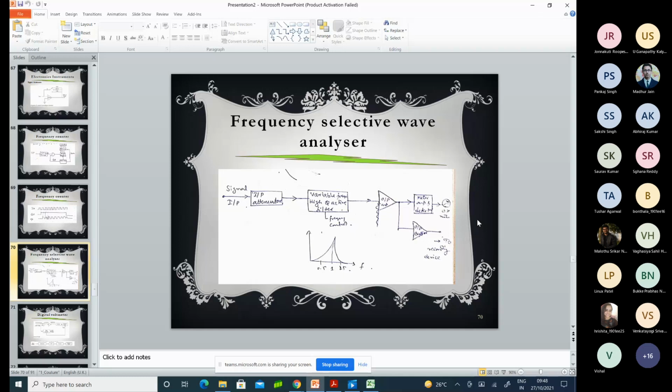So this is the main philosophy, that if you have a signal in the time domain, it must be represented in the frequency domain. This is a very important representation, because you can see how many harmonics are present and what the amplitude will be. Based on that, you can process it, and after you amplify it, you can determine the different distortions and the bandwidth of the amplifier required, everything, based on this.